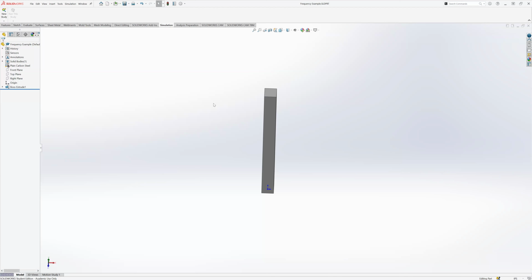Very similar in this case, what will happen is if your vibration is very close to the natural frequency, the amplitude of the vibrations, or how much it vibrates distance-wise, will keep increasing. It might start small and then it'll go bigger and bigger and bigger until the entire system or component will just rip itself apart. If you've ever seen people shattering glass with sound, this is what happens. They're vibrating it at very close to its natural frequency, or at the natural frequency.